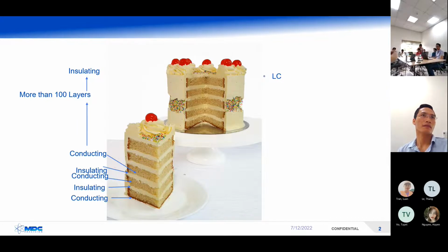Once that's done, we then lay down the next layer, which is the insulating layer. And we do the same thing then. We etch out the pattern for the insulating layer. Now we have some wires and an insulating layer, and we put down another conducting layer that we will etch more wires into. We have to get the top conducting layer to connect to the bottom conducting layer, right? So after you put the insulating layer and form it, we drill little holes in places where we want the next conducting layer to connect to the bottom conducting layer.